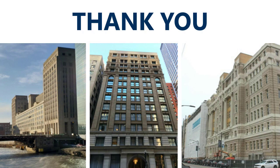Okay, next question. How do you handle dangerous conditions that are seen during the survey? Well, the first thing is to notify the owner right away. If we're on the wall and we get to it and it's a fall hazard, we have to address it right away, whether it's removing it or having a contractor stabilize it, pin it, net it.